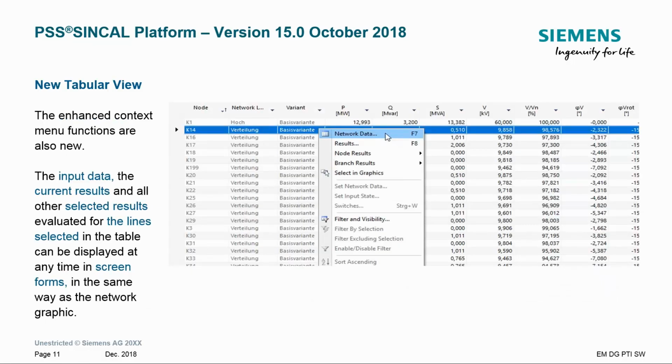And you will see there is another option now available in the tabular view. When you move to a specific element or node, and then in the context menu with the right-hand mouse button, you can directly link to the network data itself, or to the results, or to the nodes and branch results as you want to. That's a direct link between the tabular view and all the other tables.